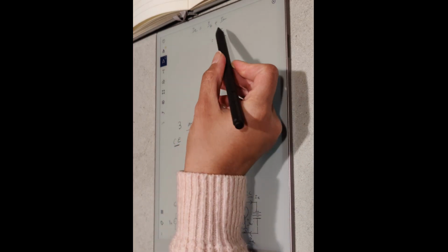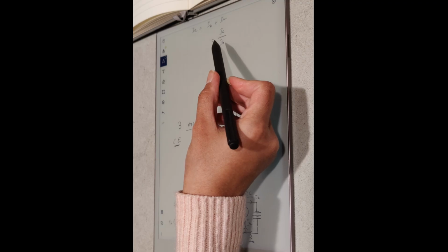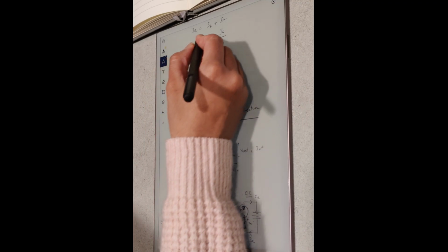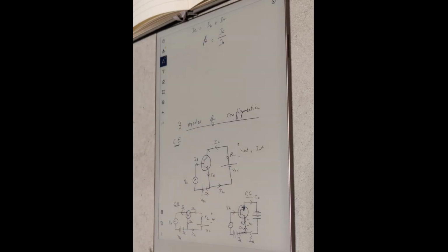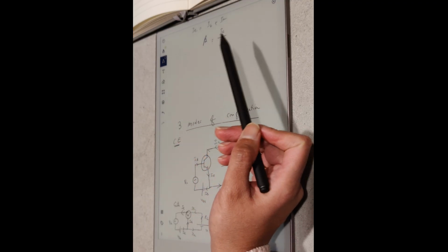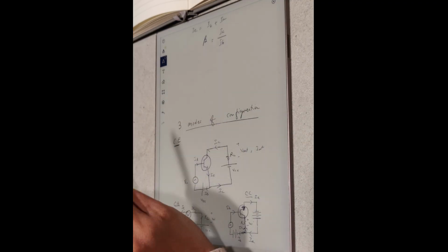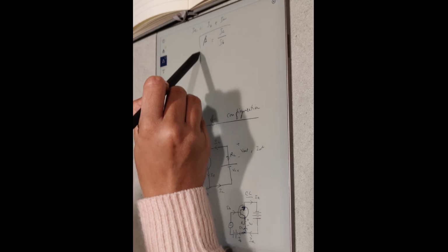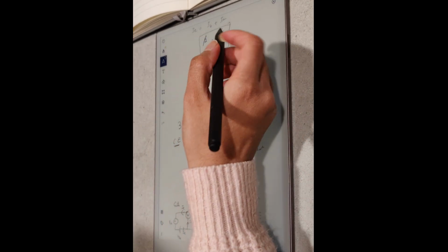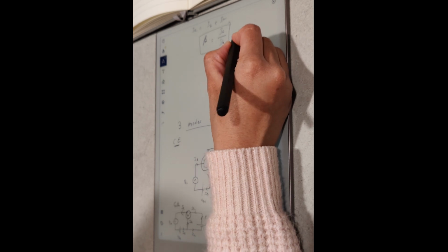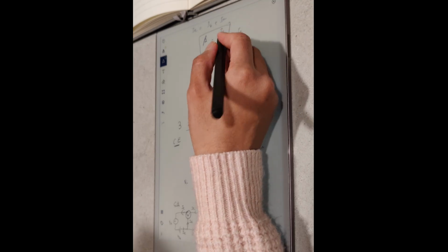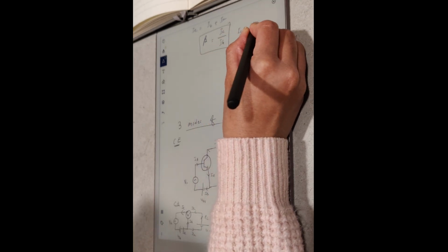So this is just output over input in terms of the current, and there is a term that defines it, called beta. A lot of times this beta will be given to us, like when we look at the data sheet for a transistor, it will tell you the value of beta. And this is a very, very important relationship, because as we have seen before, IC is only possible when you have some IB. So IC is equal to beta times IB.